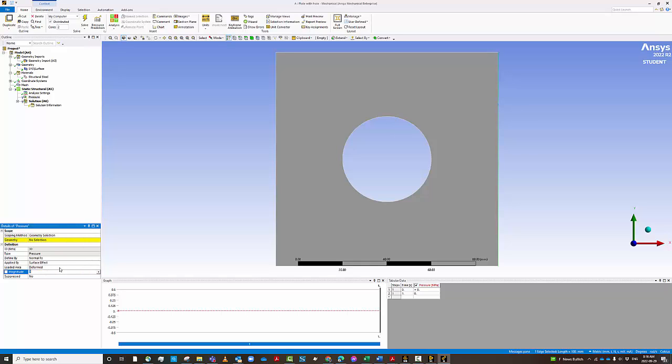So pressure, when you apply forces, basically force is positive in the positive x-axis and negative in the negative x-axis, and the same thing for y and z. Pressure is positive when it is toward the surface. It is negative if it is away from the surface. So in our case, we are going to put minus, I think, 1000. Okay. Now this is megapascal, right? Megapascal, remember, is basically newtons per meter squared times 10 to the 6, or newtons per square millimeter, right? So unit should be consistent all the time.